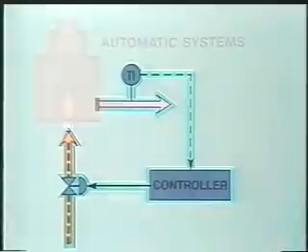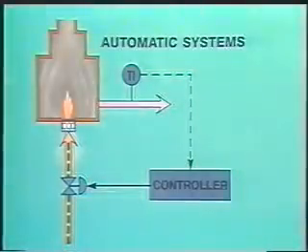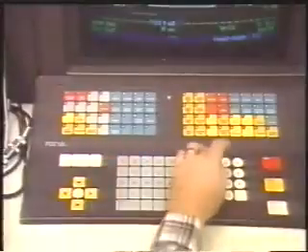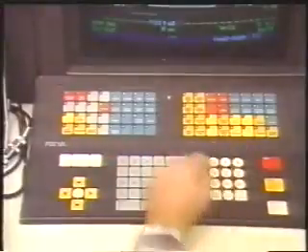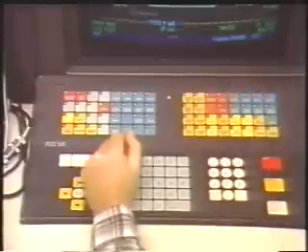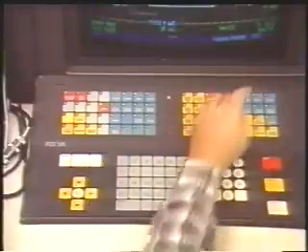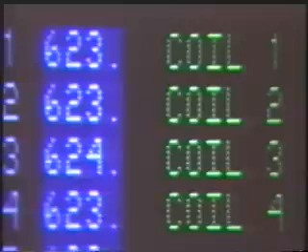This, in turn, will cause the furnace to overheat and could cause coking in hot spots. If the operator suspects this is occurring, he can check the individual outlet temperatures for each pass of tubes. If these are above normal, this would indicate that the measuring or transmitting device has probably malfunctioned. The operator would then manually control the amount of fuel to the burners to prevent the furnace from overfiring.